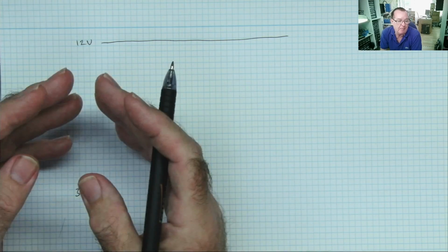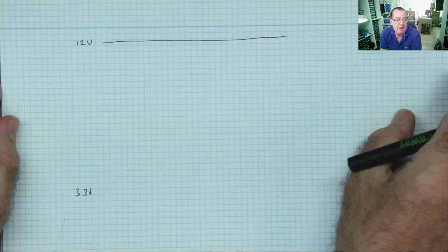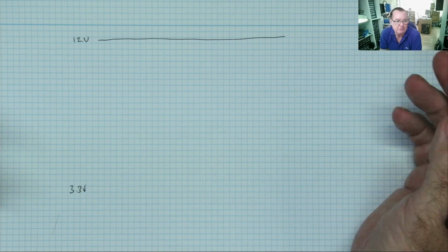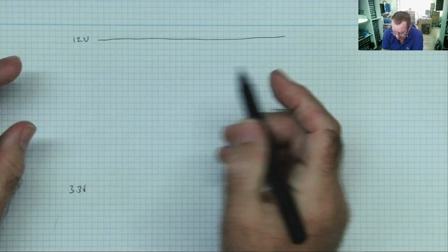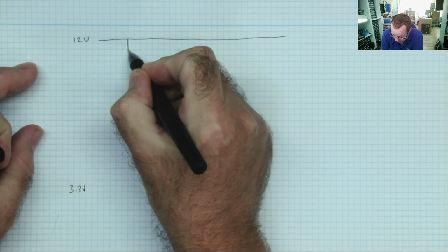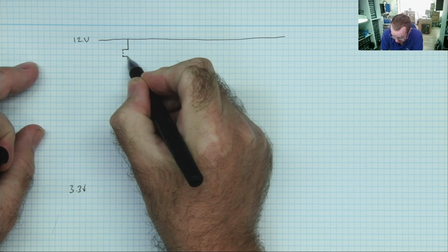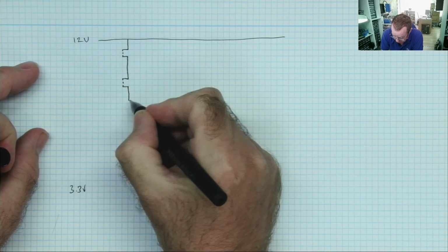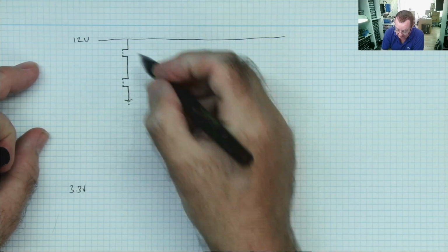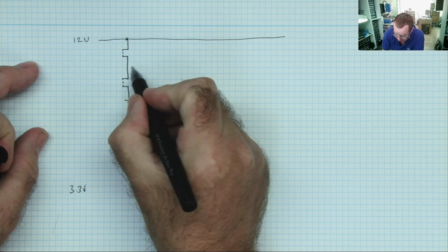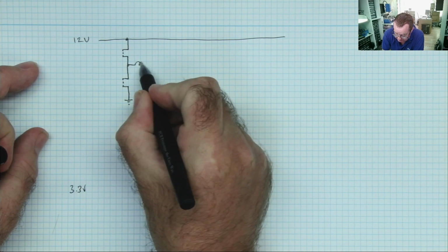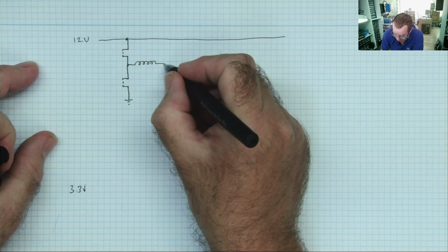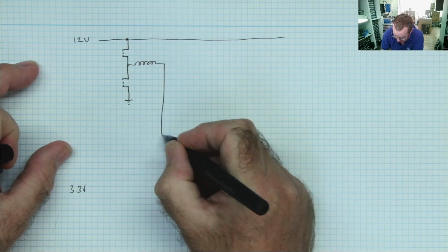And we also have them where there are many phases. Another word used, or rather initials if you like, for this is VRM, which is voltage regulator module. But they all work basically the same. Without going very technical, we have two MOSFETs like this, wired in series, and going to ground. This is the symbol for ground, okay? This is the 12 volts. And the two MOSFETs connect to a coil. These are the inductors I was measuring from to ground, and the inductor generates the output voltage out.